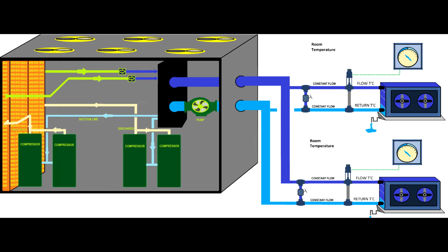So that is the place where the refrigerant goes from the high pressure side to the low pressure side. When the refrigerant expands, it absorbs heat. So here's the trick. That black plate heat exchanger is the place where the refrigerant absorbs the heat from the water. By the way, water and refrigerant do not touch. So that's the plate heat exchanger. You have some tubes which divide the refrigerant from the water. Probably most of you already know this, but some people might not.